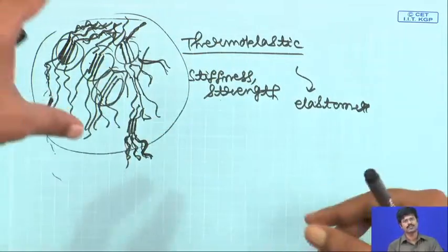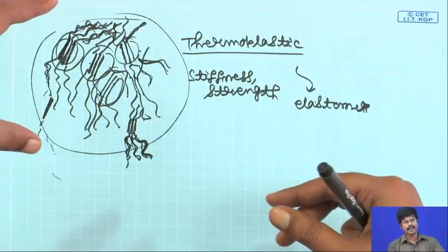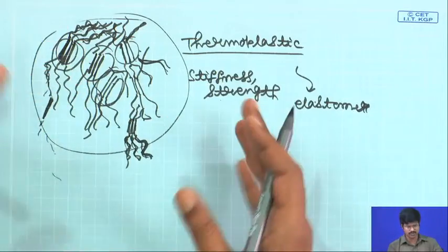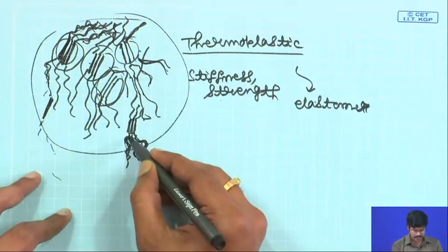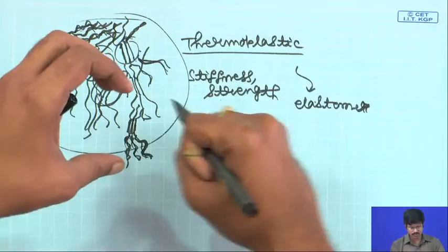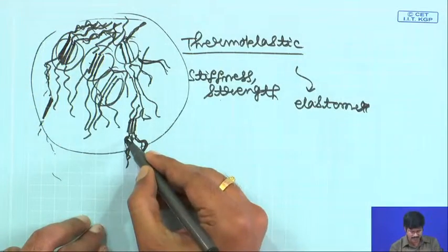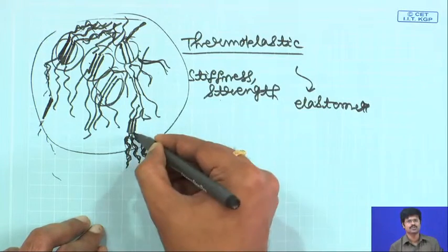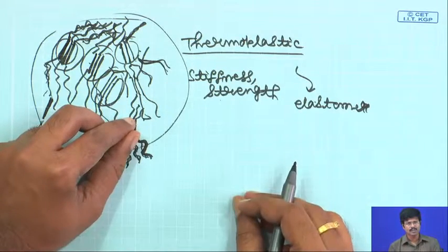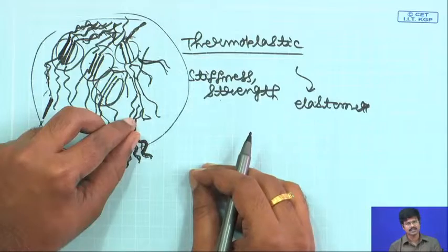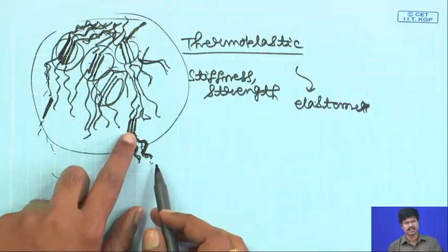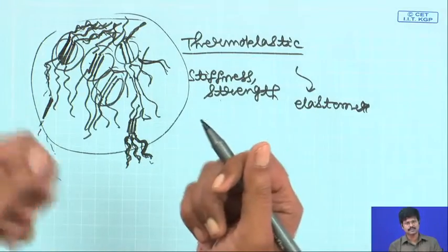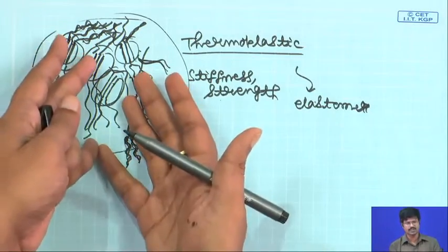Until they are extended to their complete length, you can keep stretching, and when you remove your applied outside force, they can come back, because they do not start to flow when you keep applying force. Ultimately these soft blocks are covalently bonded to the hard blocks. So, they just do not go away. The flowability of the material is restricted because the soft block is connected to the hard block, and when you release your applied stress, it can come back to its original situation.